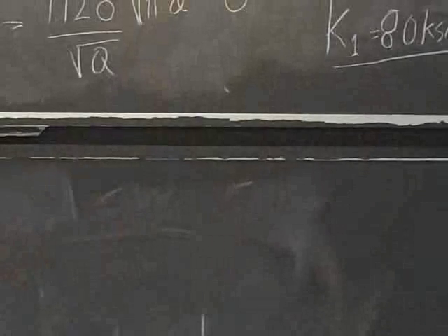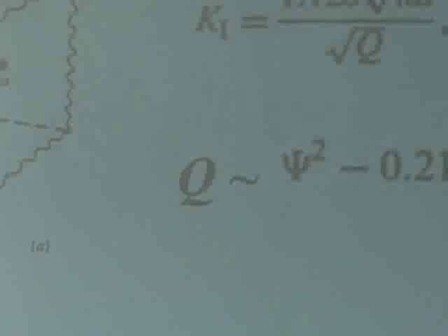So if you have a thinner wall, and you could do it with even cheese. If you take cheese and you start cracking the cheese, it doesn't pop on you. You need to keep pulling on it to break it. So that's what we're talking about here when we're talking about a thin plate. It doesn't matter how sharp the notches you put in it. You can do a fatigue pre-crack in it. When you start loading it, it will tear on you, as opposed to really fracturing and making this popping noise.